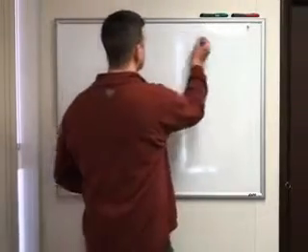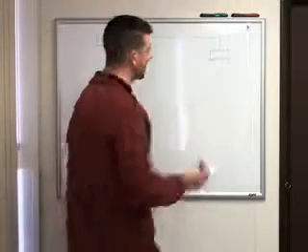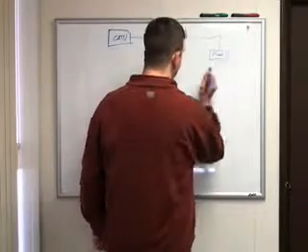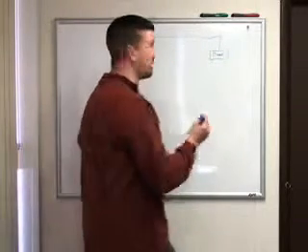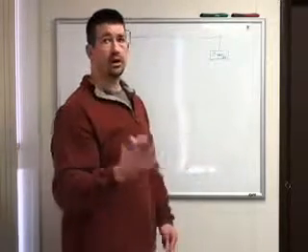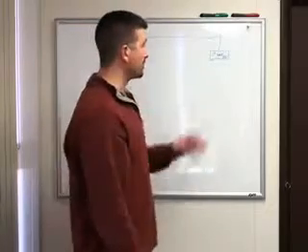Now in this case, the distance of wire between the 2-way and the 8-ways is only going to be a couple of feet, so we don't have to worry about calculating the loss on them. The 2-way has a 3.5 dB loss on it. As we said before, you want to look at your manufacturer's spec sheet and find out the insertion loss, or look on the front of the splitter to get that.